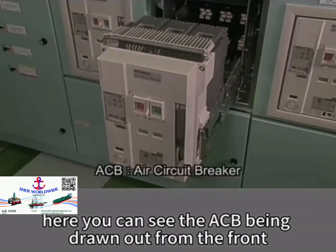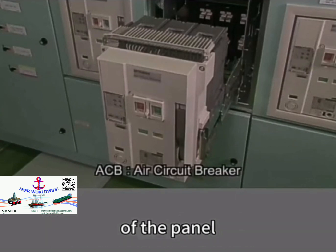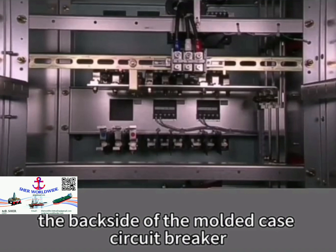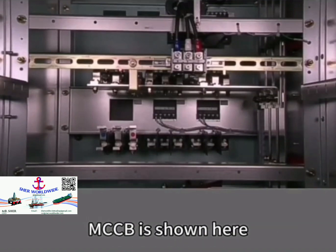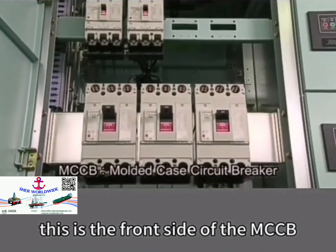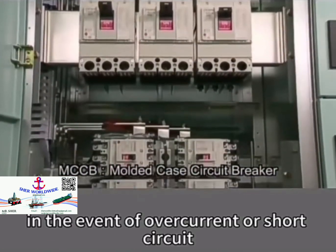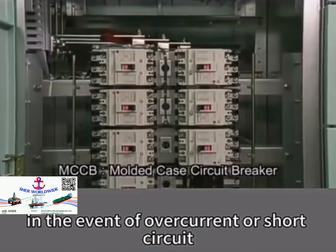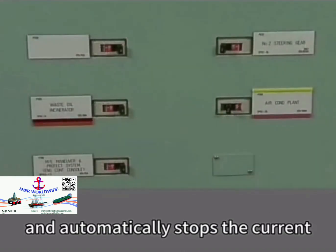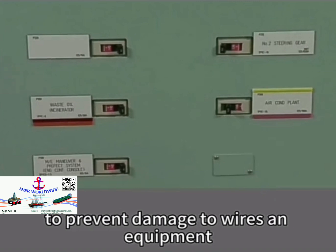Here you can see the ACB being drawn out from the front of the panel. The backside of the molded case circuit breaker, MCCB, is shown here. This is the front side of the MCCB. In the event of overcurrent or short circuit, the MCCB trips off and automatically stops the current to prevent damage to wires and equipment.